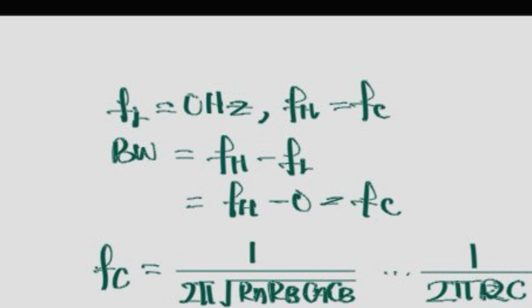The roll-off rate is negative 40 decibels per decade because it is a second-order filter. One order means negative 20 decibels per decade. This means that beyond the frequency cut-off point, the filter starts to attenuate the signal amplitude. The further away from the cut-off, the weaker the output signal becomes for that frequency.